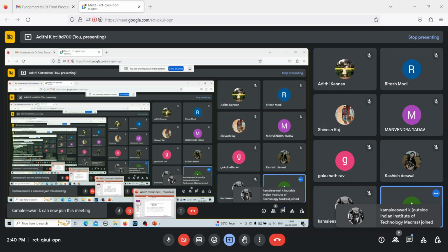In this case, Deborah's number is a dimensionless number often used in rheology to characterize the fluidity of a material under specific flow conditions. Deborah's number is basically the relaxation time, or characteristic time period of the material, divided by the time period of observation.